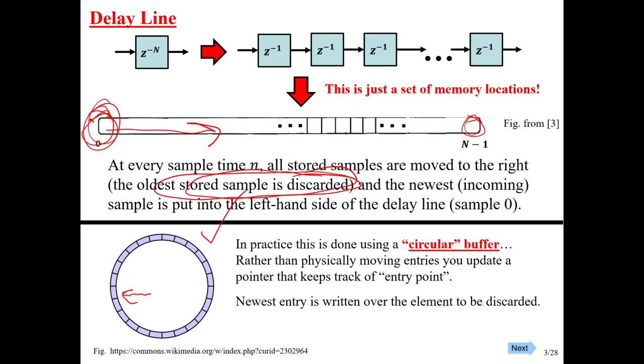And this is now the current oldest sample. So that was here. We've effectively moved everything to the right by just moving our pointer. Then our newest sample that comes in gets written here, and it writes over the oldest one. And so now everything works properly.